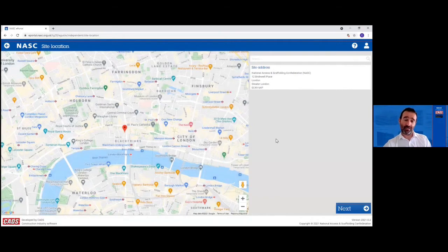And then behind the scenes, this calculates the site wind factor. This has been significantly improved since TG 2013. So a lot of the options that you had to choose manually in TG 2013 are completely automated now. So for example, the wind factor calculation will pick up whether your site is in town, and if so, how far within the town in each wind direction, and how much sheltering that it gets from other buildings, for example. So the wind calculation is completely automated.